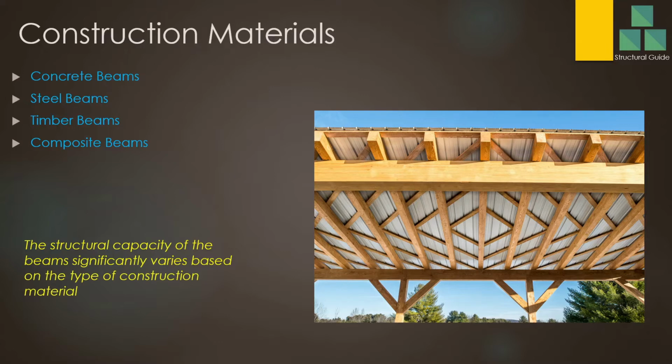Composite beams. These composite beams are most common in steel structures. These beams are made from the composite action of the slab mostly. When you put the steel decking on a steel beam underneath, the stiffness of the steel beam can be increased by considering the stiffness of the steel decking slab. There are methods: we insert shear dowels and make it take the combined action. Those kinds of beams can be considered as composite beams.